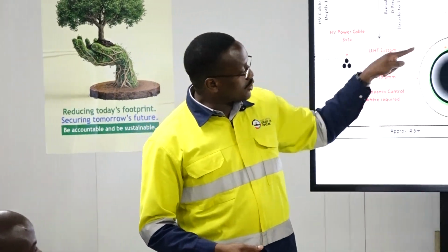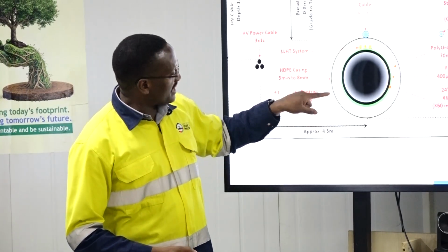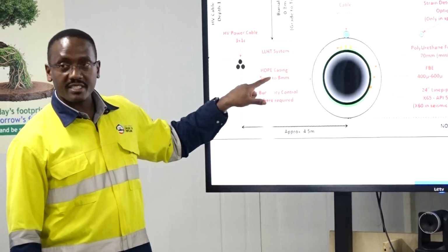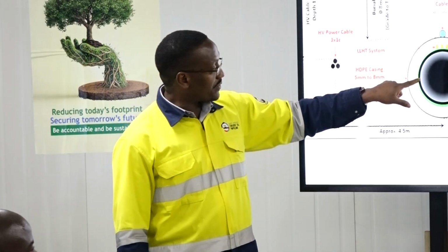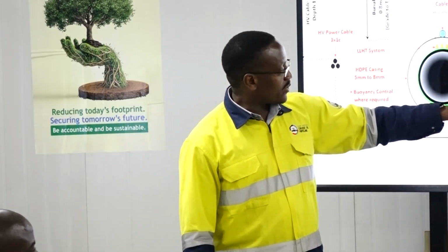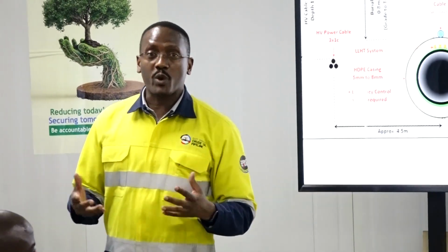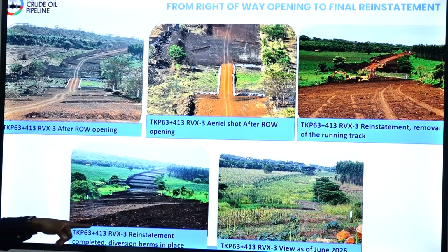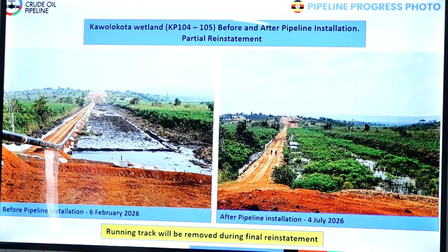So on top of the foam, we put high density polyethylene, this black one, around 5 to 8 millimeters thick, and it depends on where. Even the pipe itself is how many inches? We're talking about 24-inch, but it also depends. The thickness of the pipe depends on where the pipe is going to be placed. If it's a fault zone, you need a thicker pipe. If you're going under a national road, you may need a slightly thicker pipe. So this is the fiber optic cable.